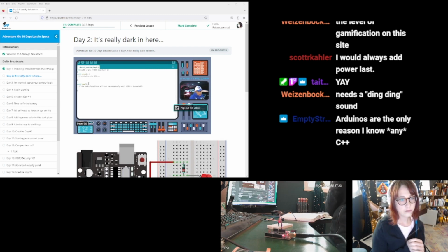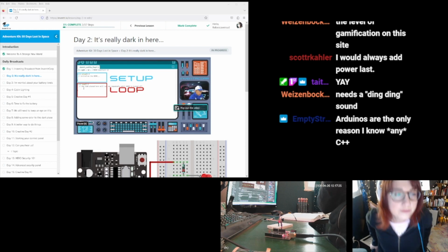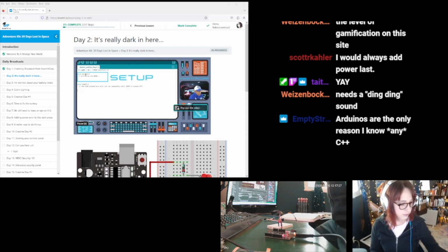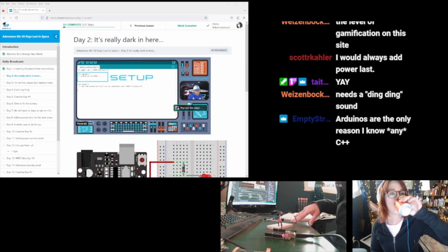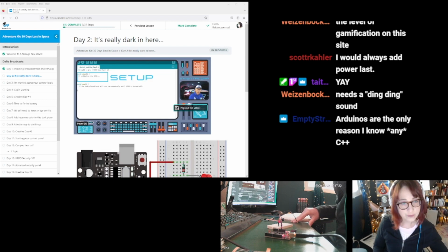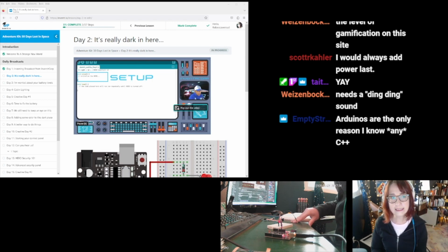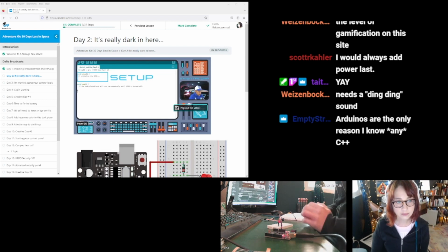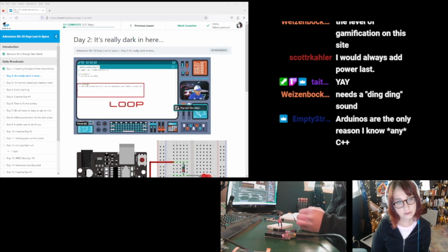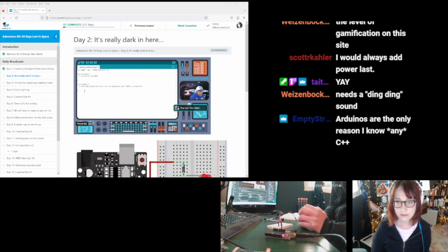The two routines, setup and loop, have different purposes or different functions. Setup runs once, and as its name indicates, its purpose is to set up the Hero, to get started on its job. And so it only executes once. Whereas loop, which we'll get to in a little while, is designed to run repeatedly over and over again, and will not stop until you turn the Hero off. So let's get started by putting some statements into setup.